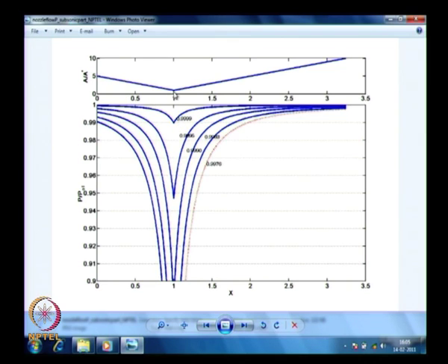then this throat section is going to have a pressure of 0.99. I am thinking about 10 power minus 1, 10 power minus 4 drop from 1. Yeah, it is a very small change in Pb by P01 value, and that is giving you a 0.99 P by P0 at the throat location. Okay, but if you look at most of the other places, it is almost 1. It will probably be ending in 0.9999, that is what it will end up with.